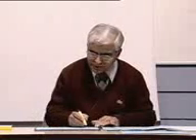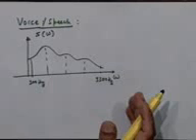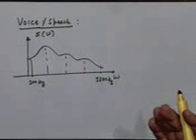So for most telephonic communication purposes, the band from 300 hertz to 3300 hertz is the one which is important, right? So that is why we say that a voice band channel has a bandwidth of about 4 kilohertz.